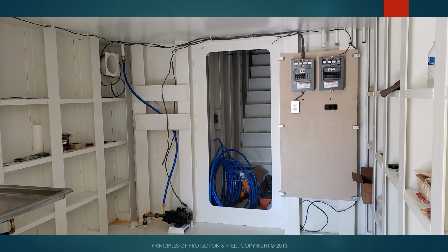The best way I found, this is an S9 shelter I designed. The best way I found to do it is to put a centrifugal pump here and have it draw water from under the shelter, and you can turn it on and off as you need it. And this is always serviceable. And underneath this is a basket strainer, and here's a 4-inch pipe plug, so in case it ever gets clogged up for some reason, you can take that off and you can reach under.